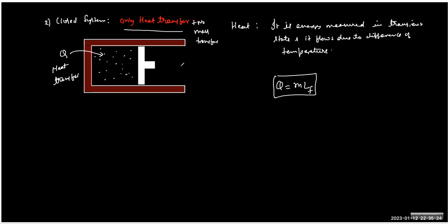So when you compress something, expand something, when there is a boundary which is moving, a gaseous system confined in a boundary and you're moving the boundary, such a motion of boundary is actually an example of work transfer. Because I have told you that work is a boundary phenomenon, and when we say a boundary is moved against some resistance, work is being done. So work transfer can happen with any kind of system. The only criterion is it must have a movable boundary. Understood?